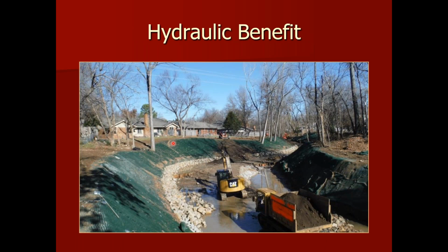The hydraulic benefit of it, though, has sort of been assumed. We haven't really, up until the last several months, had the opportunity to isolate the anchor itself and the combination of anchor, TRM, spacing, and hydraulic load in the overall performance of a TRM system.